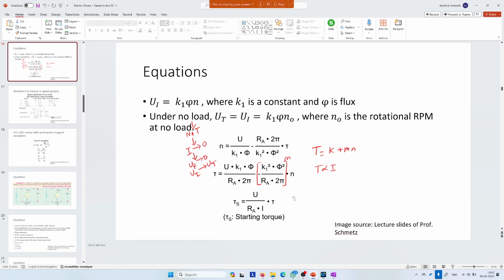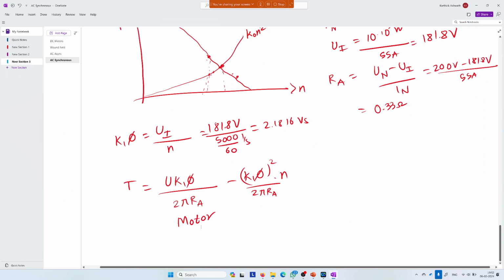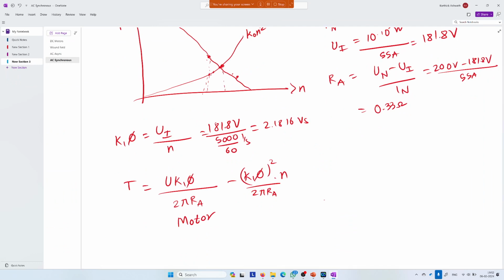So torque. I'm going to use that same equation, and this is what the motor is giving. My target right now is to find the steady state RPM. Like I mentioned previously, steady state is the point where a equals alpha equals 0. So RPM is constant and there is no net force or net torque anymore. And that is happening when both the torque supply and demand are equal.